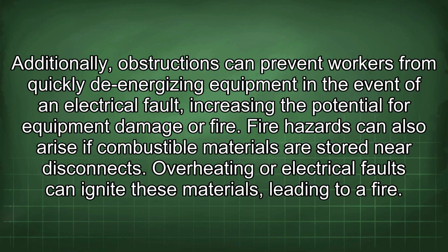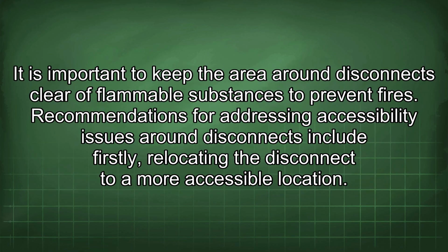Fire hazards can also arise if combustible materials are stored near disconnects. Overheating or electrical faults can ignite these materials, leading to a fire. It is important to keep the area around disconnects clear of flammable substances to prevent fires.